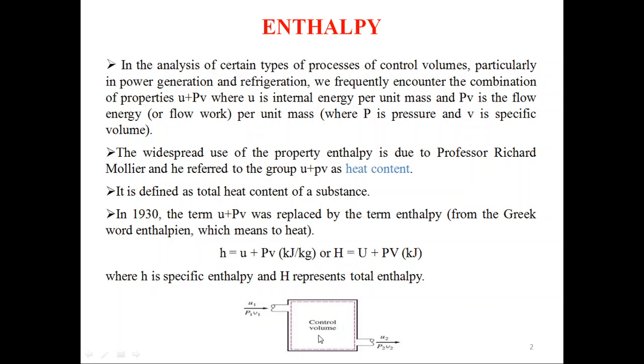You can see the figure in which we have a control volume or open system, and fluid is flowing into this system and also exits the system. So there will be an internal energy associated with the fluid as well as the flow energy associated with the fluid. So the term u plus Pv is generally encountered in this type of case.